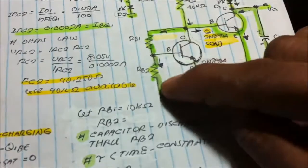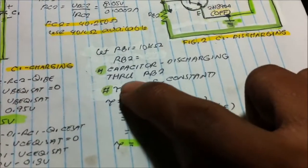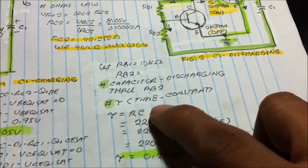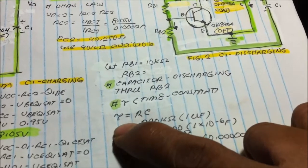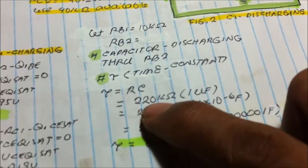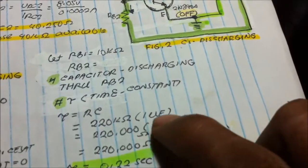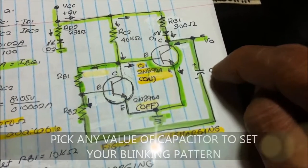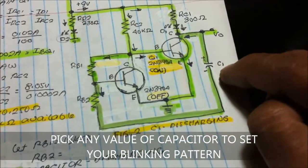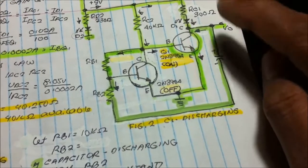It is arbitrary because when you're going to compute for the speed of charging and discharging of the capacitor, using the time constant tau is equal to resistor times capacitor. I'm using 220 kilo ohms, an arbitrary value, and I'm using 1 microfarad. Also, the value of the capacitor here is arbitrary. You can pick any value you want to adjust the blinking pattern.